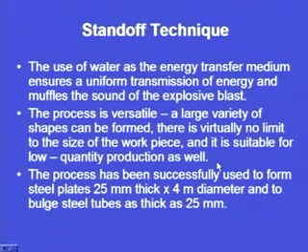The process has been successfully used to form steel plates 25 millimeter thick and 4 meter in diameter, and to bulge steel tubes as thick as 25 millimeters. So, this standoff technique is an explosive forming technique. In explosive forming we can either deform a sheet or we can deform a tube.